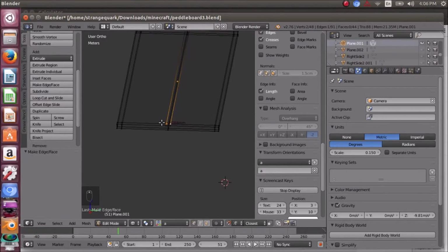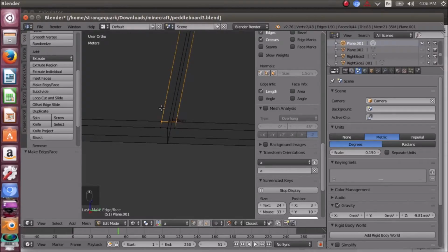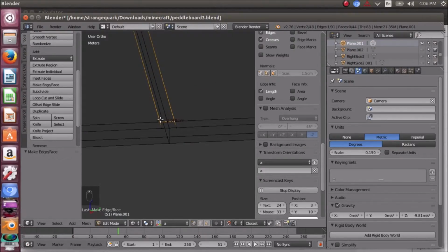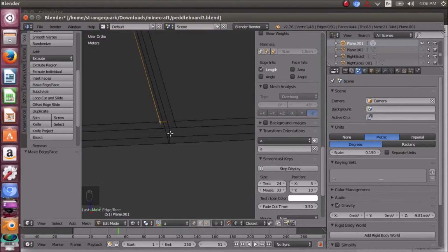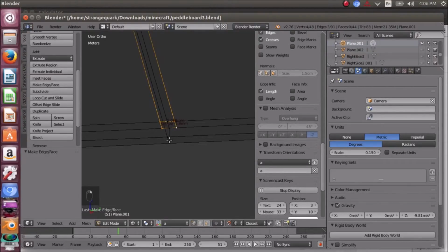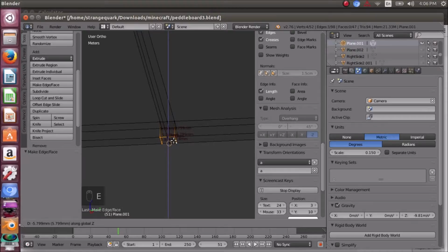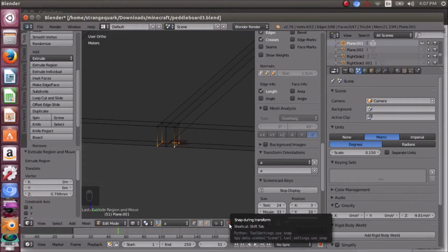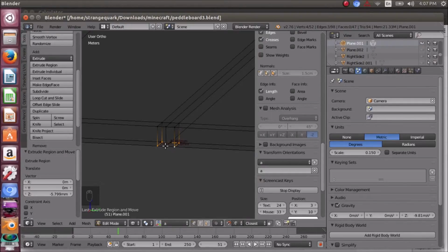But yeah, we would go through the process of, once you create the wall thickness there, you'll have to extrude these sets of vertices on either side of the line, the subdivision line, on a Z restricted basis, and I just selected them all, and then we already have the snap during transform set to vertex, so all I had to do was, on a Z constrained extrusion, select this vertex, and it automatically sends that group of vertices right down to the bottom there.